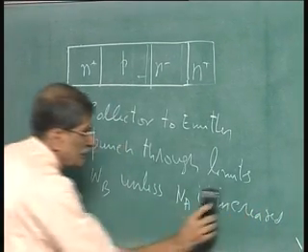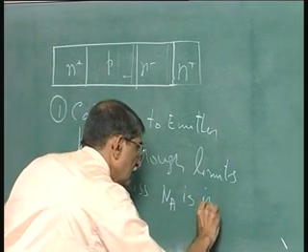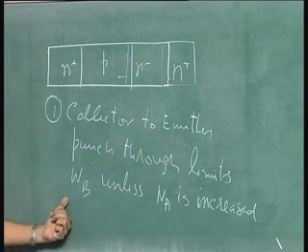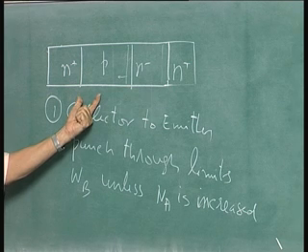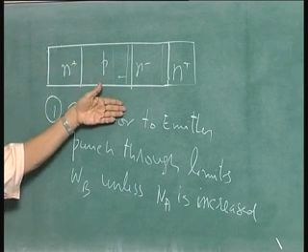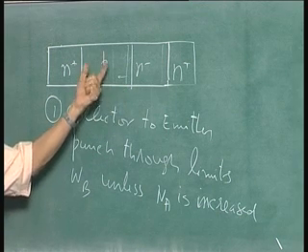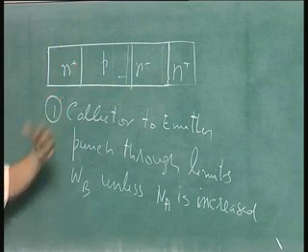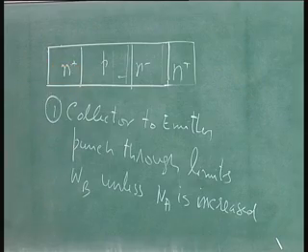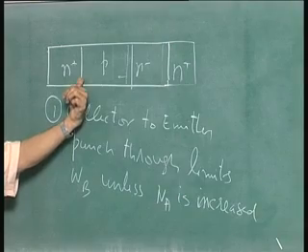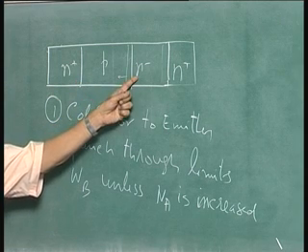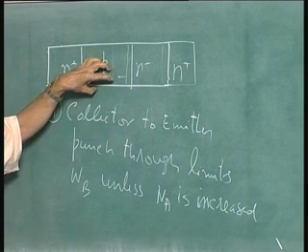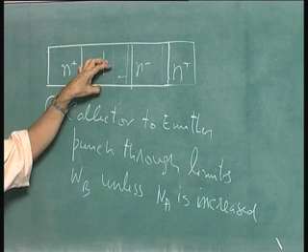In other words, you must increase NA if you have to go to lower WB to avoid this problem of depletion layer punch through. You may say I will have a non-uniformly doped substrate, but the punch through voltage depends upon the total doping concentration here. After all, if you reduce the base width, unless you increase the doping concentration, the integrated doping concentration will not be sufficient, because when you have plus charges on the depletion layer, it calls for minus charges. The minus charges are limited by how many dopants are present here. So, when you reduce the base width, the number of dopants present is less, unless you increase the doping concentration.